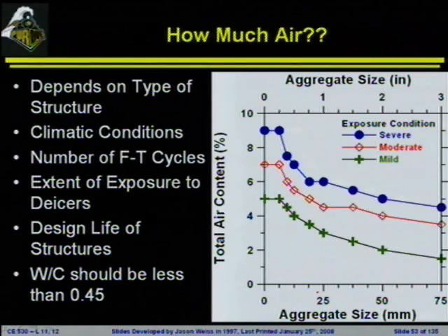The paste volume. So as we increase the aggregate size, the paste is going to decrease. And one of the most crucial things that we're going to discuss in this class is that while we do all of our measurements in the field talking about the total volume of air, the air is not there to protect the total volume of the concrete. It is there to protect the paste. The air is there and it's only going to work on protecting the paste.